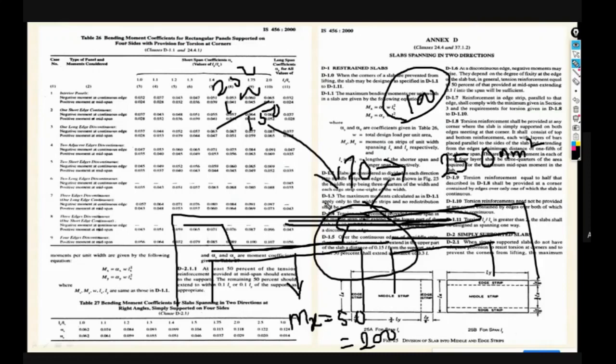First we analyze that particular element, and then we check the behavior of that element under all these loads: earthquake load, wind load, gravity loads, whatever loads you are considering for the design. As per those conditions we design, focusing on the bending moment, then shear forces, then deflections, and as per all those criteria we design that particular element.